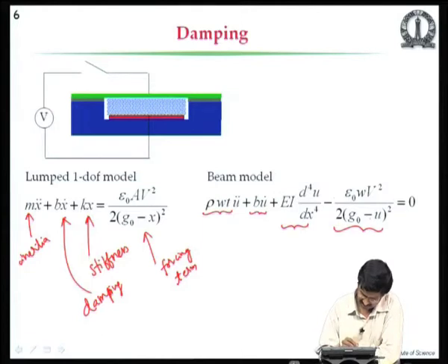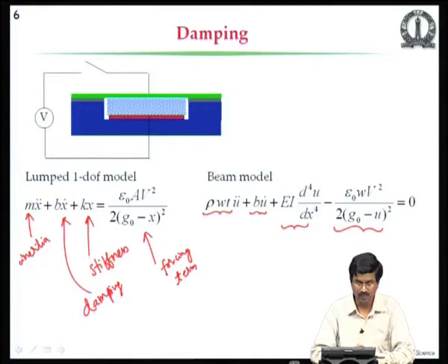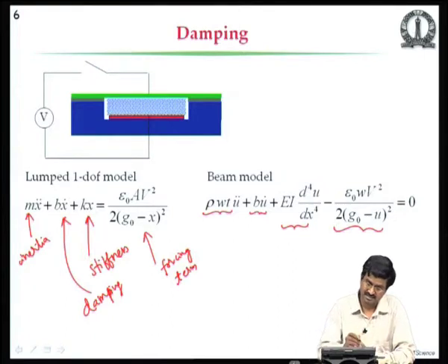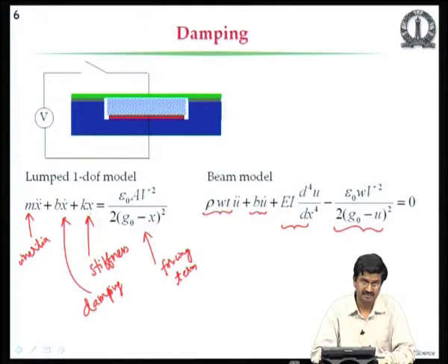That can be on the right hand side or minus on the left hand side. So, we get the dynamic equation. We have discussed how to get K, we have discussed how to get M also, because when you want to get equivalent inertia, we use the fact that the kinetic energy of the deforming system should be the same as the lumped model's kinetic energy, just like the strain energy of the lumped spring is the same as the strain energy of the elastic body.